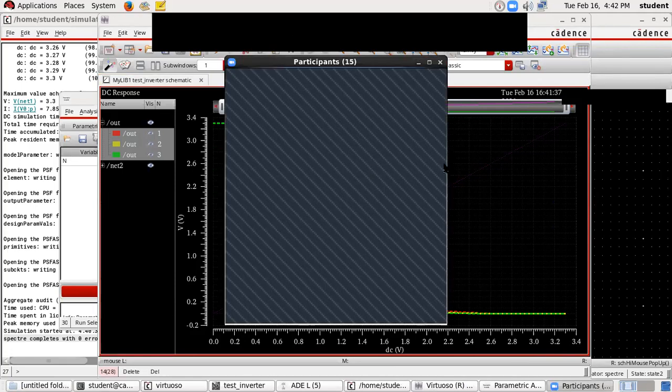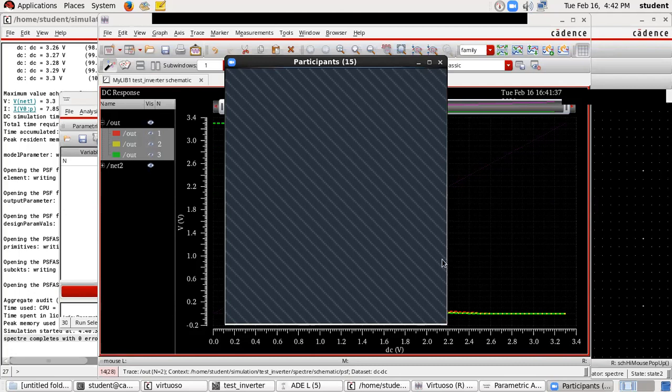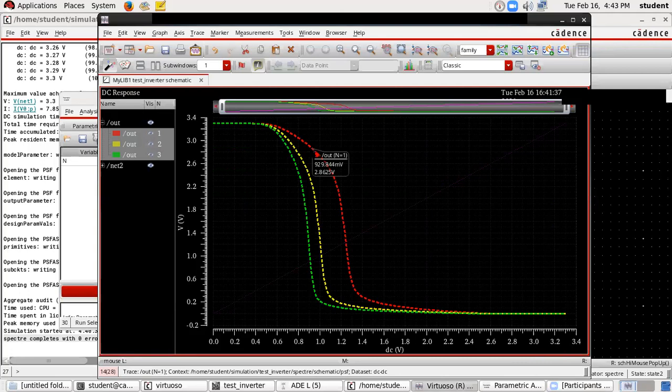Right, so that is what it is all about the inverter. Again, in order to design this, you have a lot of equations. You can calculate that root over 1 by Kr is equal to whatever that equation is, put different values in it, obtain a value of Kr, obtain a W for NMOS or PMOS, fix the W.